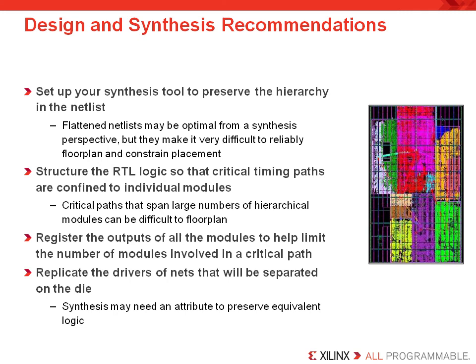If you are going to use area constraints to improve your design speed or use partitions to maintain some of your results, here are some important recommendations which you can follow. Set up your synthesis tool to preserve the hierarchy in the netlist. This can be done by selecting the Keep Hierarchy option in the synthesis options. Flattening your netlist may be optimal from a synthesis perspective, but it makes it very difficult to reliably floor plan and constrain placement.